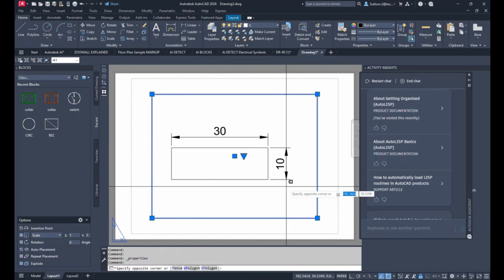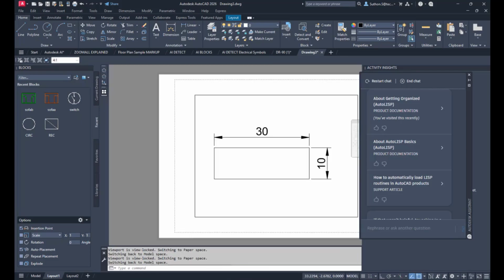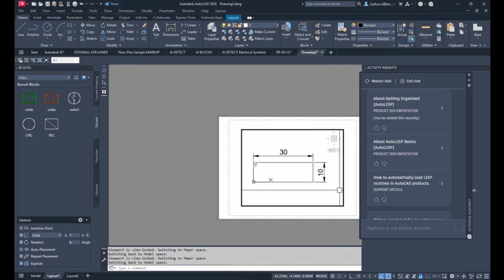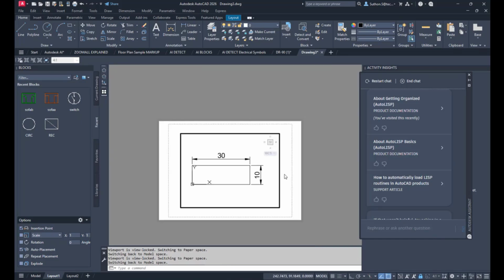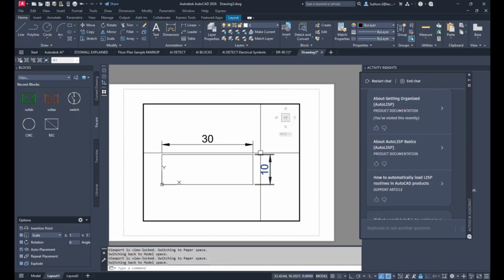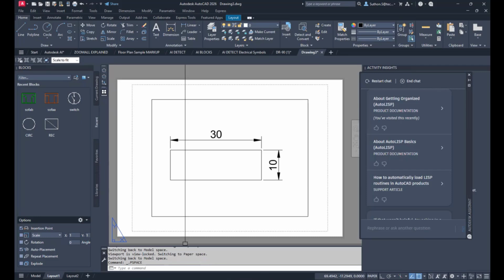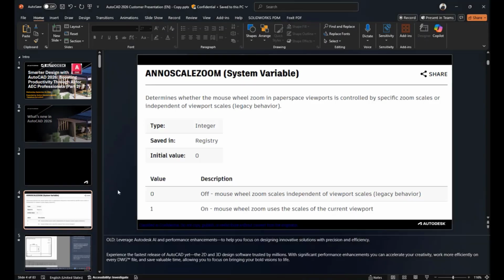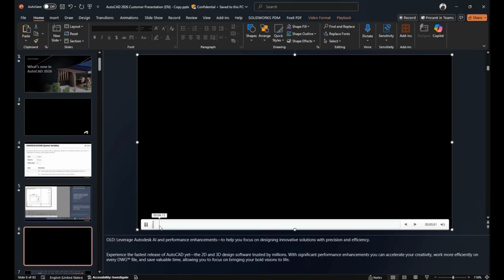That means next time you get into the model space viewport and you zoom, you pan anything, you don't lose this scale. The paper will go with the scale to keep the scale constant. You see, you don't lose any scale by zoom anymore. This trick, I'd like to warm you up with first before we get into presenting the AI. Okay, let's get back to our slide. This one I think is quite clear.